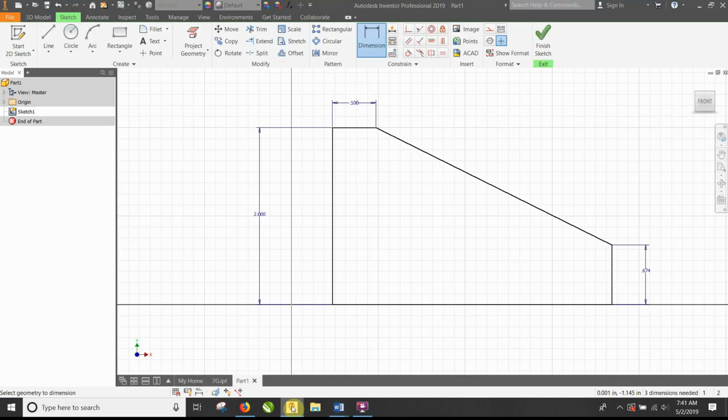Let's take a look at that. What you can do with this is type OH in, but it says that OH is the overall height, so you can just click on it and it'll come up as OH. You see how I did that? I'll do it again. I'm going to click on here. It depends on this, and it's times 0.5. Notice that if it's red, it doesn't recognize it.